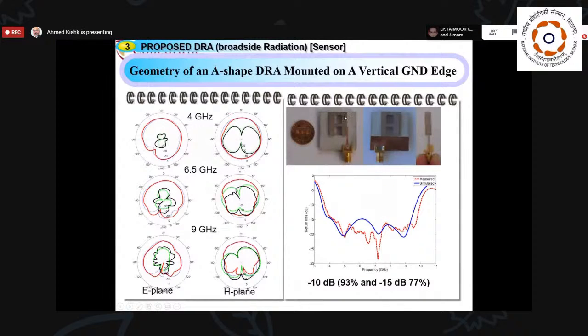But when we use a solid rectangular one, we found that there are some other higher modes that are excited. We were able to identify this mode by looking at the field distribution on the rectangular shape, and we found a very high concentration of the field in this region and this region. That means that this is acting as a resonator on its own within this whole resonator.